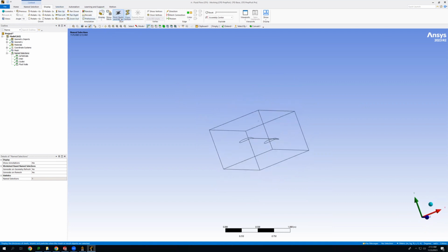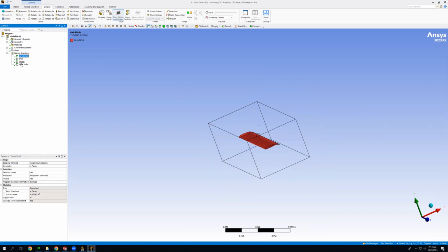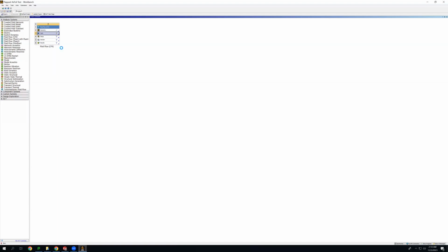You can click on the wireframe display to more clearly see what the front and back edges of everything are. After you've done that, save inside the mesh editor and exit out. After this, you're going to have to update the mesh part here by right-clicking over Mesh and selecting Update, both of which correspond to the yellow lightning icon. Now we can refresh the setup and load it by double-clicking it.